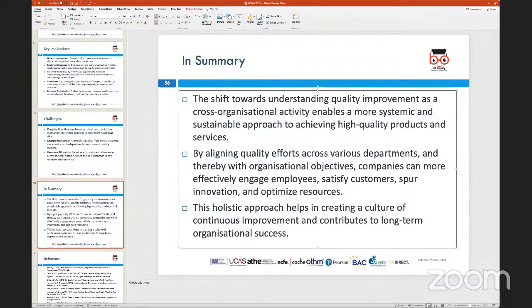Then we looked at how we diagnose variations which can occur because of the changes that can happen within product control and quality control, so the product and process control side of things. And then we looked at the reasons for these variations. We looked at the tools and techniques used to detect these variations, which are the Taguchi loss function and the Poka-yoke technique. And then we also covered briefly the Six Sigma approach to the continuous quality improvement process.